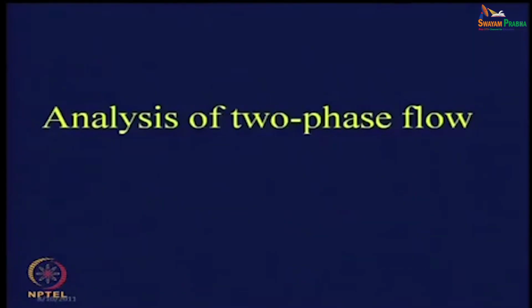We usually find pressure drop and pressure gradient, there are two things. Now, can you tell me what the pressure drop is? Usually as engineers we are interested in the pressure drop, and there is another thing which is known as the pressure gradient, which is the rate of pressure change with the axial distance. So, these are the two terms. We will be defining these two terms after we define a few more terms which are unique to two phase flow situations. Now, what are they?